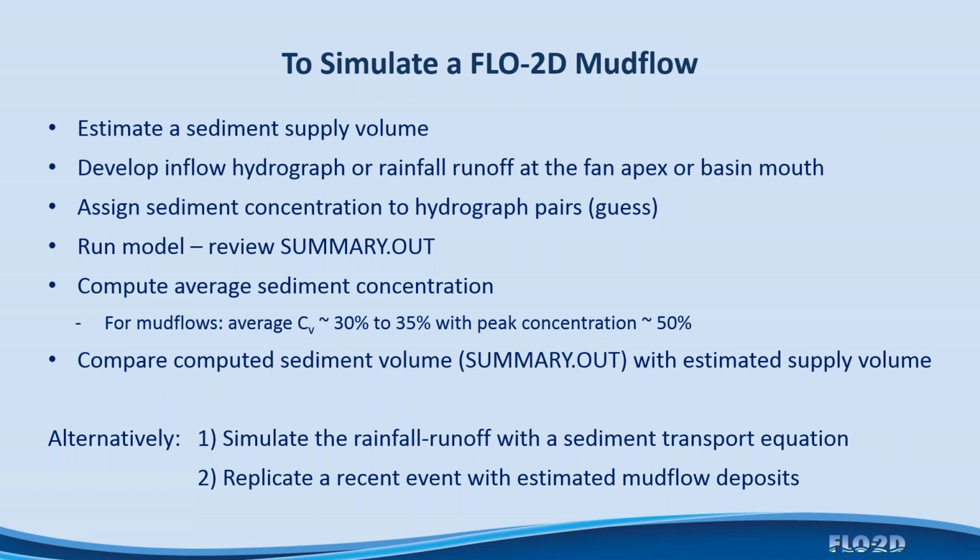Typically, I do the watershed separately just so that I have an inflow hydrograph that I can play with. It could still be in the same model, but then I put in an inflow hydrograph somewhere just above the fan apex. And so I have an inflow hydrograph that I can bulk for sediment to analyze and match with the supply. So I'm going to assign a sediment concentration to the inflow hydrograph pairs.